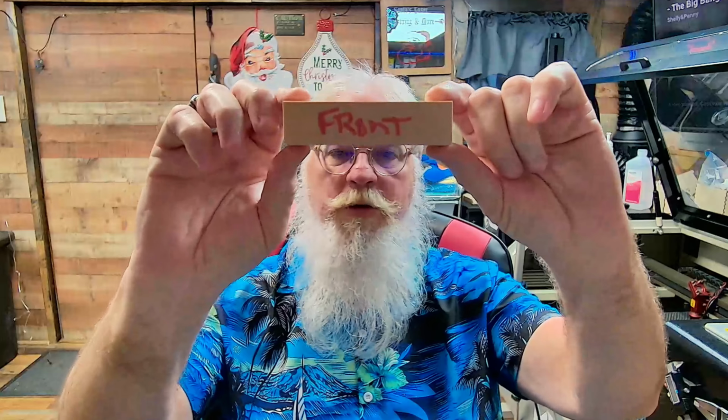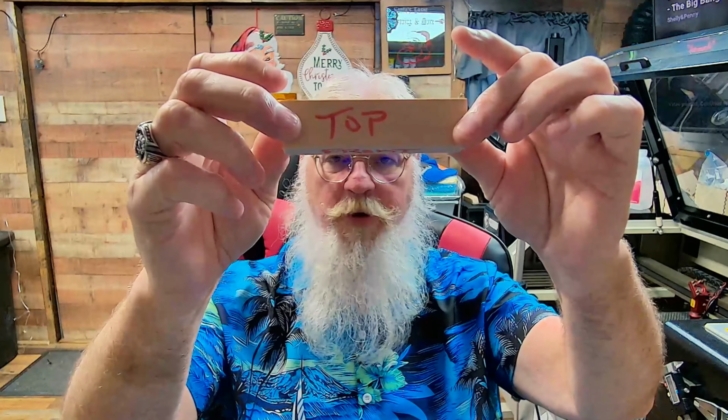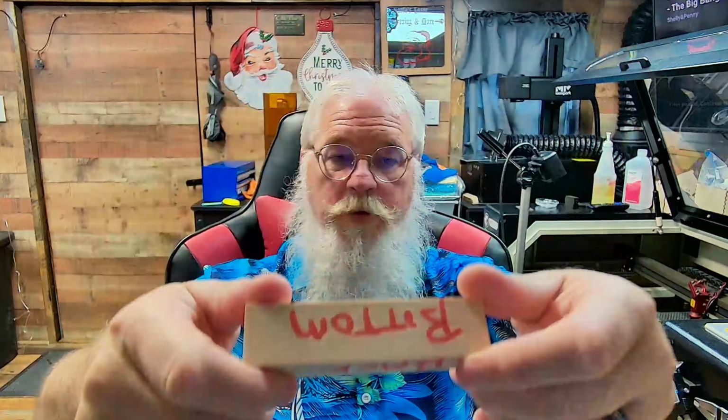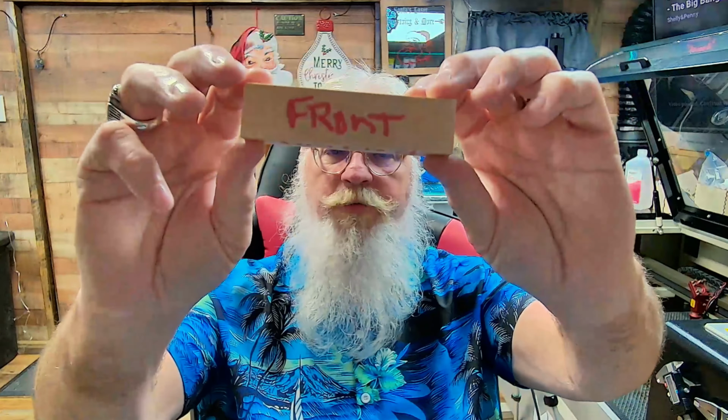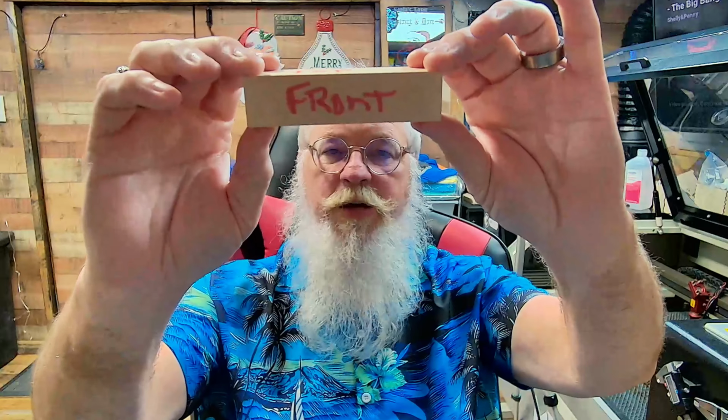So right before we get into Lightburn, you may have noticed that I had written on the block itself. And this may be one way for you to understand and help if you're at home to do this. So what we did is I wrote on the top. 90% of the time when you're looking at something, you're either looking at it from a front view or a top view to begin with, okay? So if you're looking at it from the top view, the bottom is, of course, here on the back side. That would leave the front and then the back. And then if you're looking at it that way, you're going to have a right and a left. That's very important to understand, because you can take a simple 2D drawing, draw these different views, and end up getting what you need.